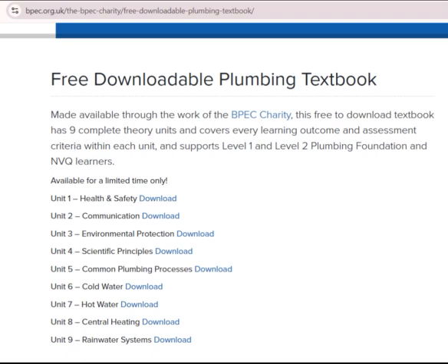A. The Honeywell Y-Plan using a 3-port motorized mid-position valve. The Y-Plan uses a 3-port mid-position motorized valve to control the flow of water from the boiler. The valve reacts to the demands of the system. If both heating and hot water are needed, the valve enters a mid-position, allowing water to flow around both the heating and hot water circuits. If heating only is required,